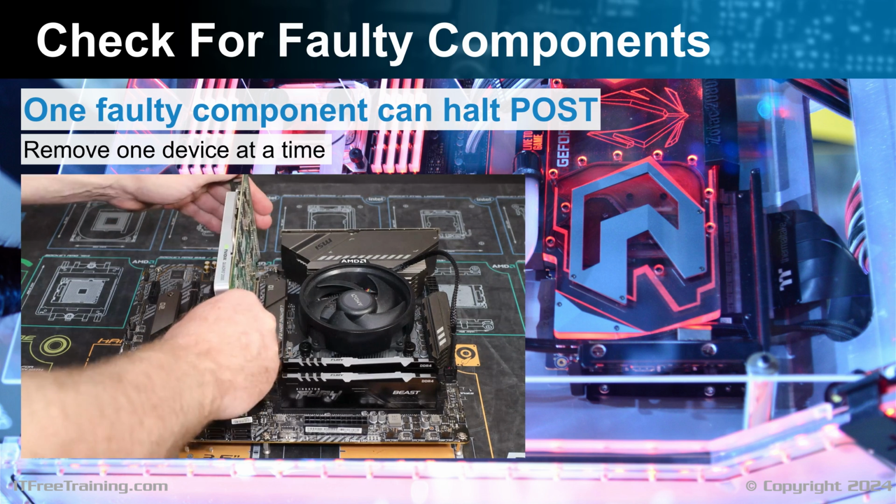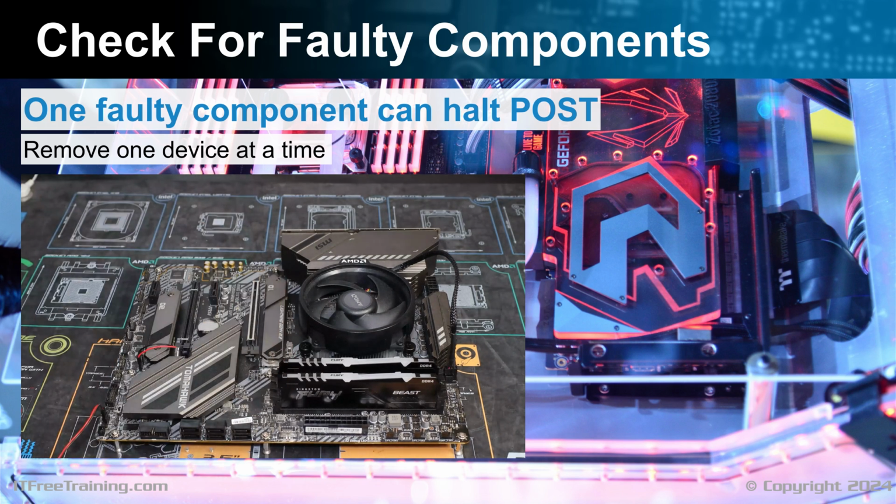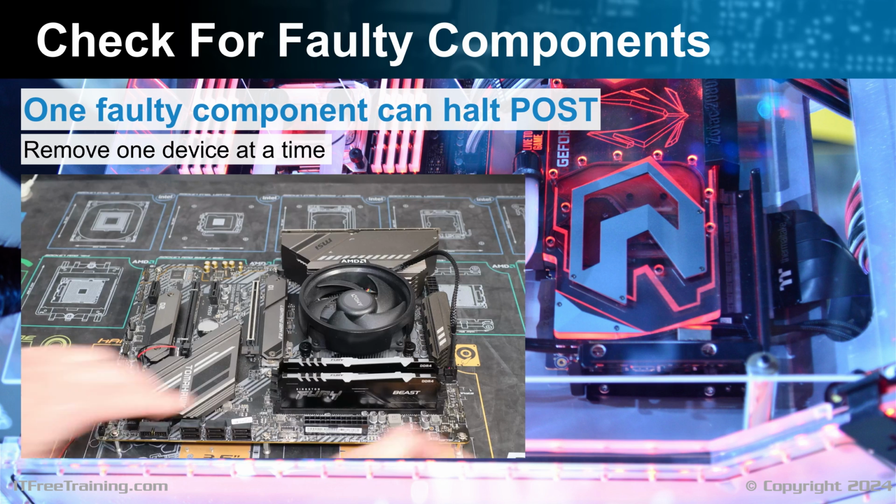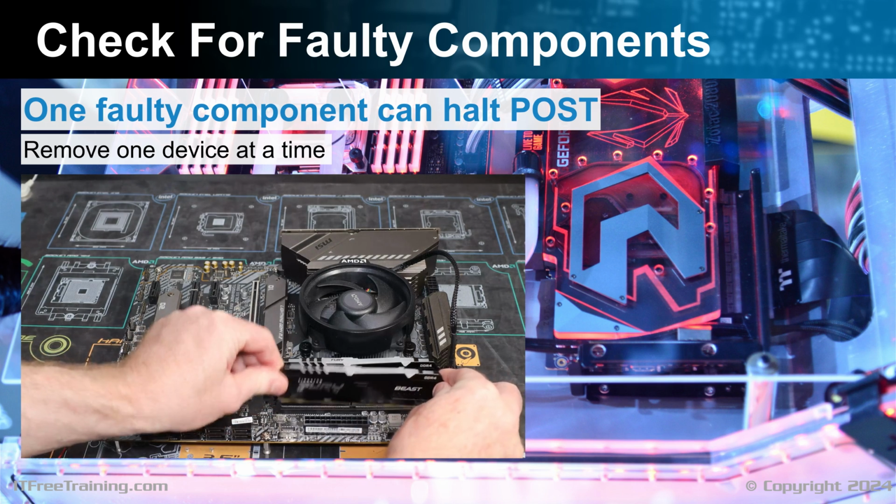I will next remove the video card, which may seem counterintuitive as the absence of the card means no display output. However, this step is crucial for diagnosing an issue. If the computer completes POST successfully, it will emit a beep or a series of beeps even without the video card. The absence of any beeps indicates a different problem. If removing the video card results in a series of beeps, this suggests the video card might be the cause of the issue.